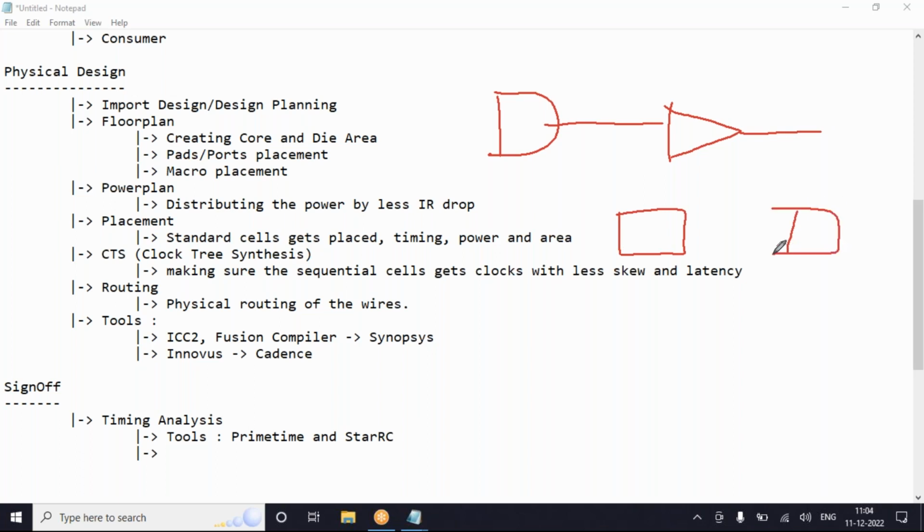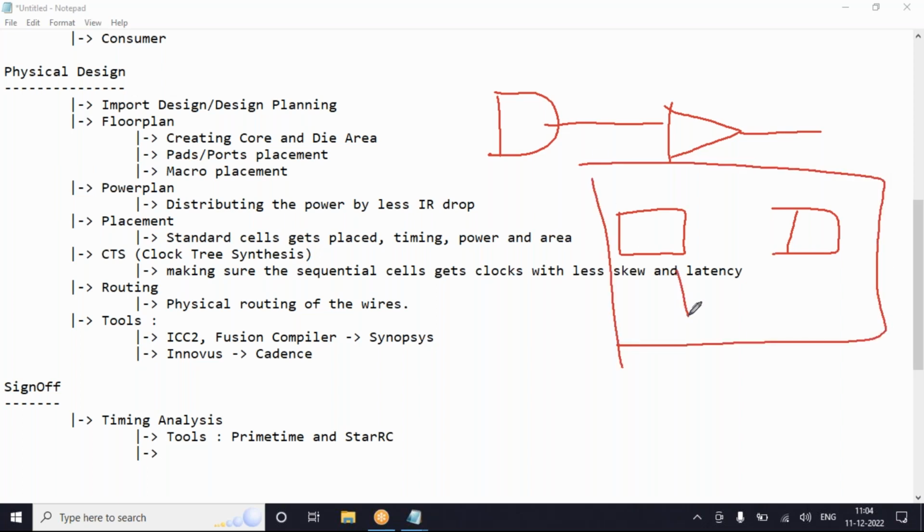That layout window is where you will be performing. You will be majorly observing the layout window. Schematic is used for your analysis. If I want to see that particular connectivity, from which cell to which cell it is connected exactly, then by using the schematic I will be able to know. In the layout window we only have cells placed, where you can see all the cell placement, routing, everything you can observe in the layout window.